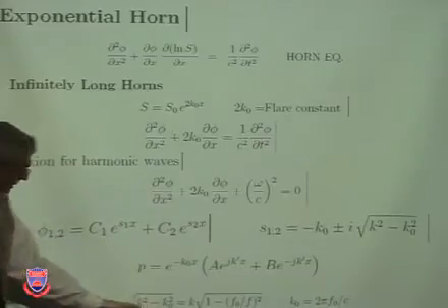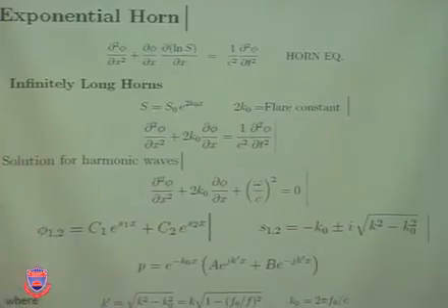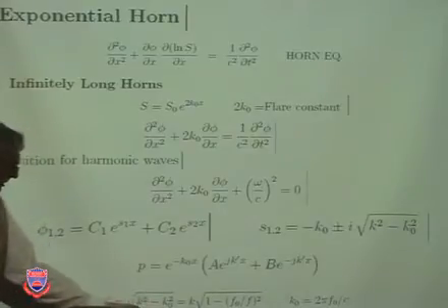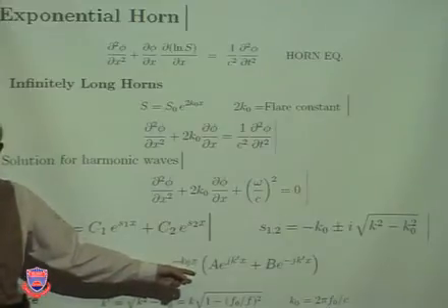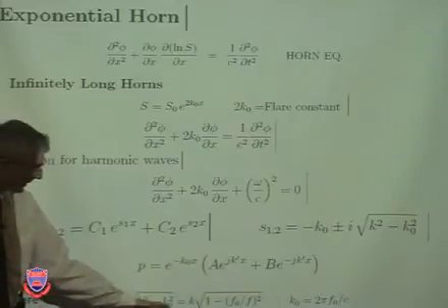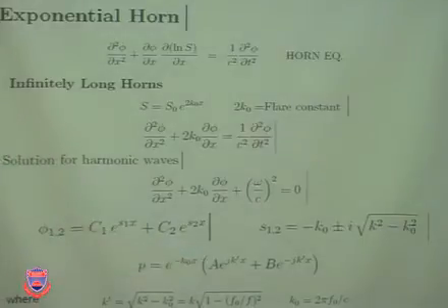If K0 is larger than K, once again, you have a decaying, double decaying wave in some ways, okay? We do not want K0 to be too large to begin with because it has a decaying effect. And if it is larger than K, once again, this becomes also decaying and there's no propagation. It's a cutoff frequency.